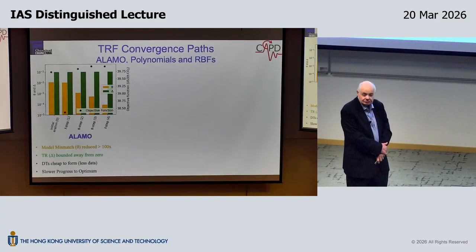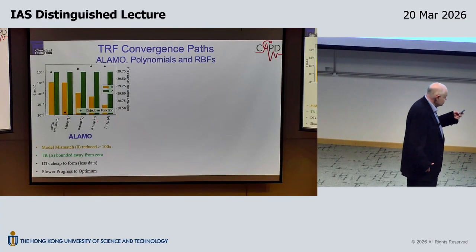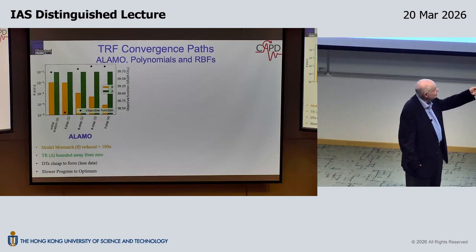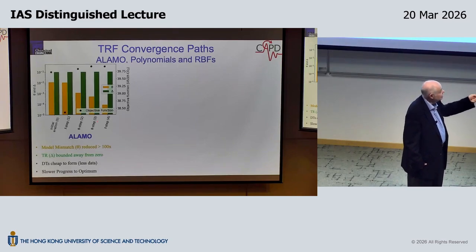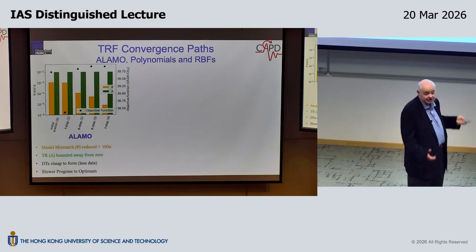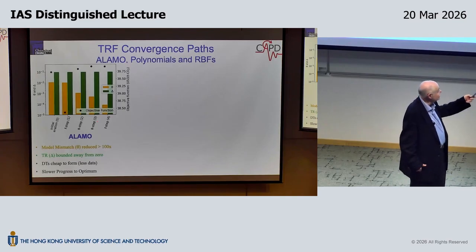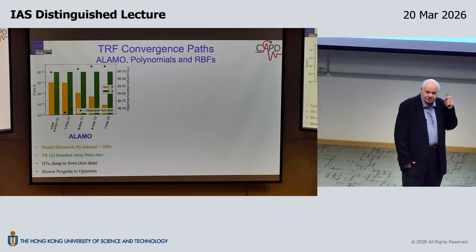Okay, good. So, Alamo, take a look at that. What I'm showing you here are the orange bars. That basically tells you what the error is in your fit between the digital twin and the truth model, okay? The green bar is the size of the trust region, okay? And it's nice if it can shrink, but if it remains large, you converge faster. And the black dot here is the objective function. So you'd start up fairly high over here, it cuts back, and then basically sends you to something lower, and this is the objective function over here. And then finally, it converges to something over here. All right, so that's how it converges.